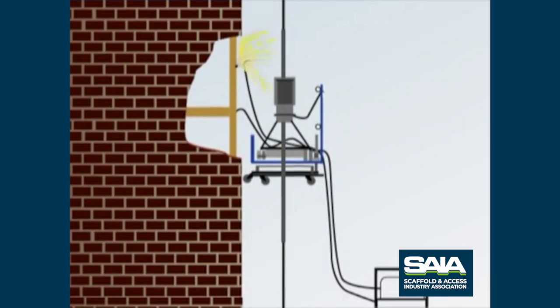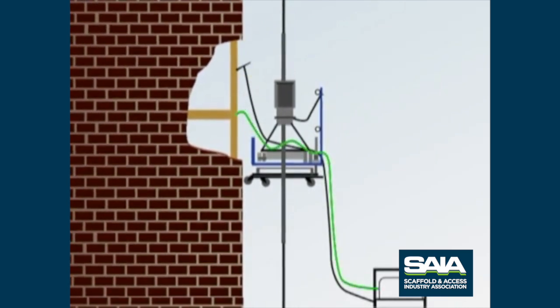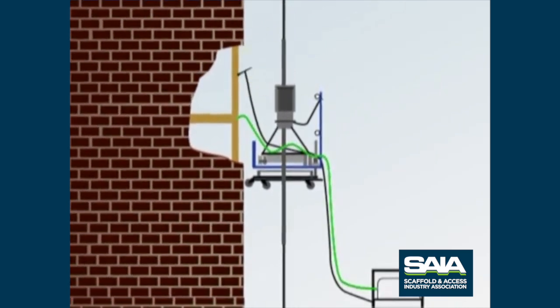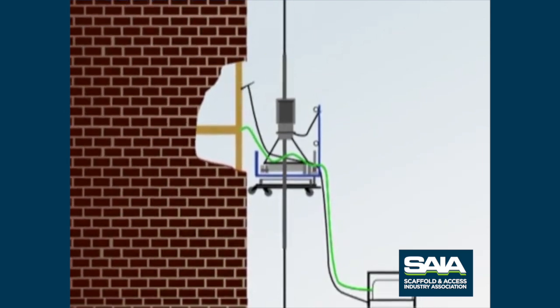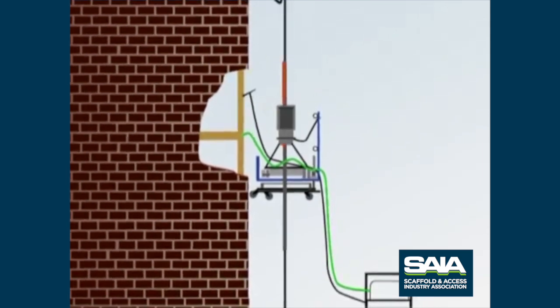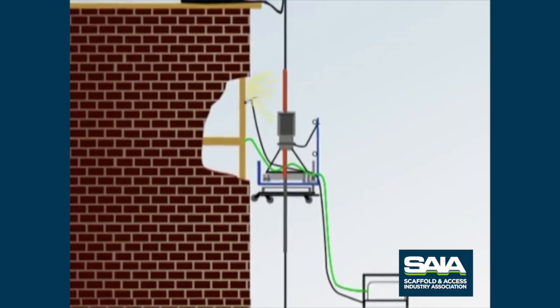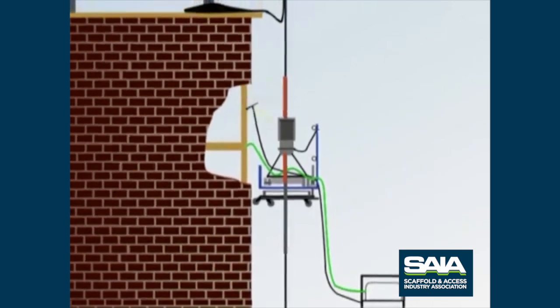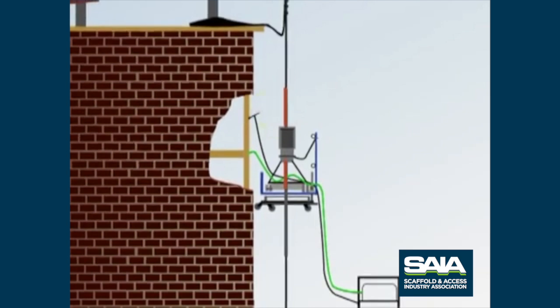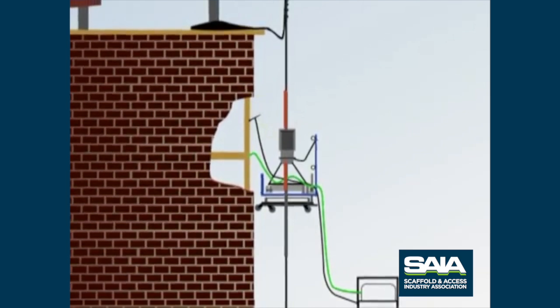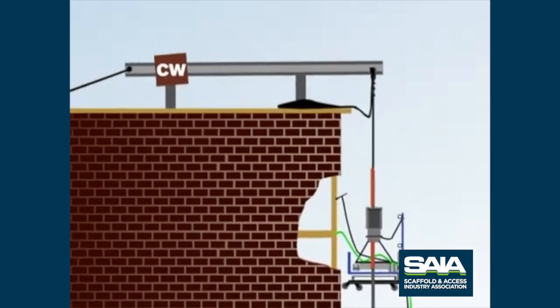When welding from a suspended scaffold, ground the scaffold as close to the work as possible. Protect wire rope with a rubber hose or some other insulator approximately 5 feet above and 2 feet below the hoist. This will prevent possible arc and damage to the wire rope should someone accidentally hit the wire rope or the stage with a welding stinger. Use extreme caution when welding from a suspended scaffold.